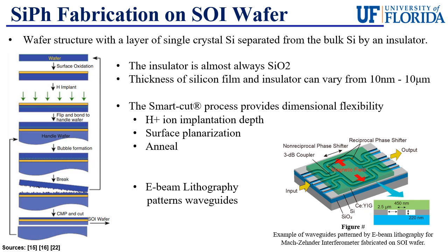And using E-beam lithography, the patterns of waveguides and other photonic components can be easily transferred to the SOI wafer by etching through the silicon film. The isolated silicon that is left will be the core for our waveguides. Then, additional silicon dioxide can be deposited on the wafer to encapsulate the silicon cores with the silicon dioxide cladding to effectively form optical waveguides on the microscale.